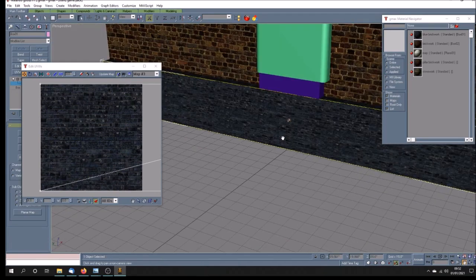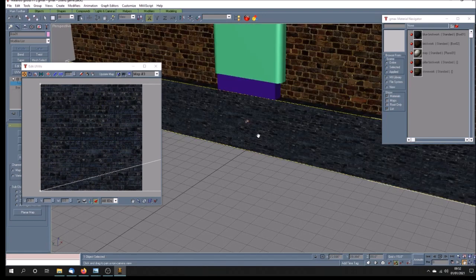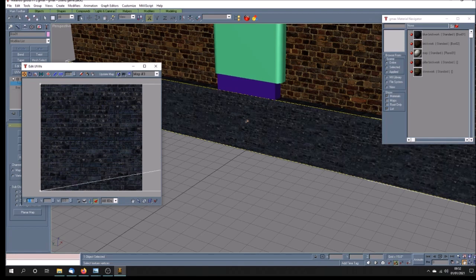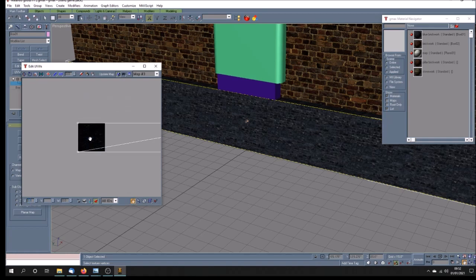No, it's still far too stretched, and also, of course, there's too many there, so let's put 6 in. I want about the length of the brick. I'm watching the length of the brick here, that's 6. And I think up the top here, I actually know that I need to have 21 courses of engineer's brick.